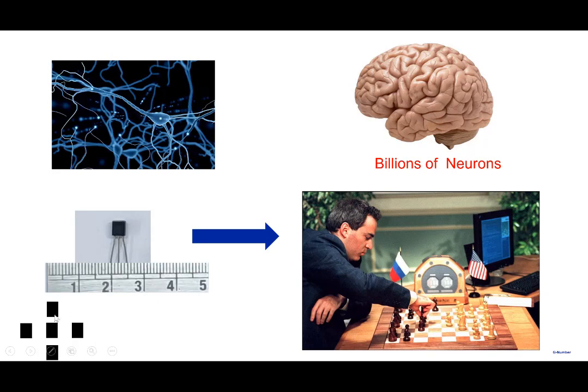So one transistor occupies an area of 1 centimeter squared, which means the transistor density is 1 transistor per centimeter squared. Let's say you want to build a circuit consisting of 1 million transistors. The area of your circuit is going to be 10 to the power 6 centimeters squared, which for a square circuit means 10 to the power 3 centimeters by 10 to the power 3 centimeters, which is 10 meters by 10 meters. The whole circuit would occupy a large room measuring 10 meters by 10 meters, which shows that it becomes impractical.